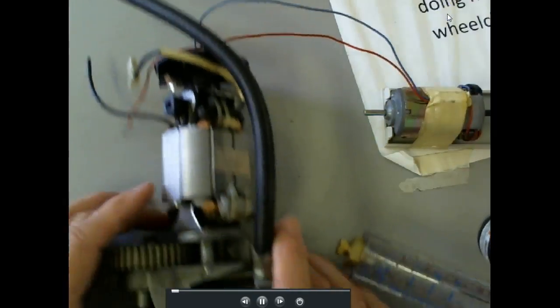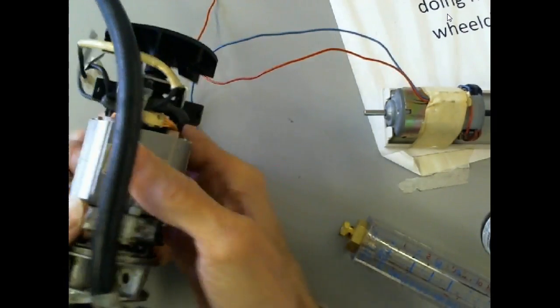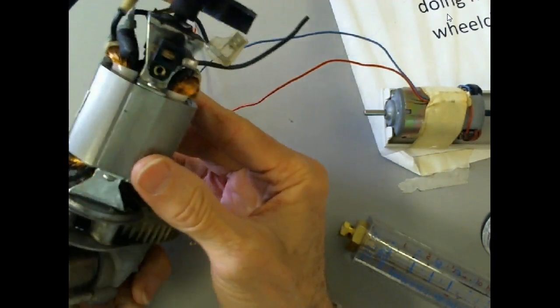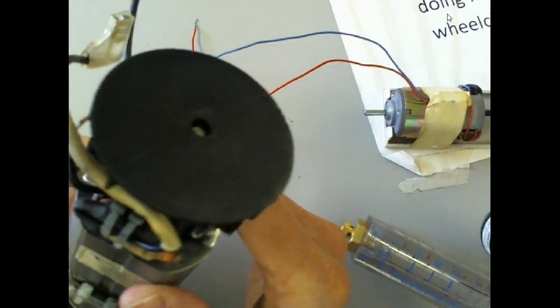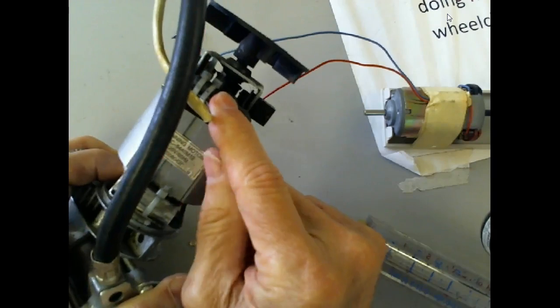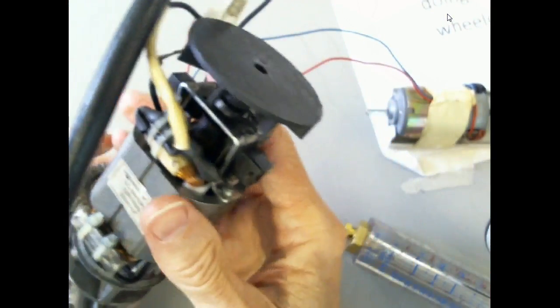So they call it a reciprocating compressor. It's got a universal motor, which is a series motor. A series motor has brushes in it, and this is what happened to this one. The brushes went bad and burned up the commutator. If you look at the commutator on there, you see it's in very, very bad shape.